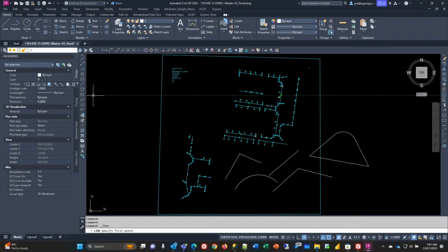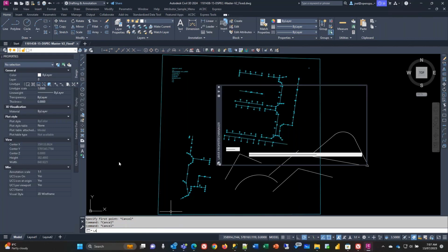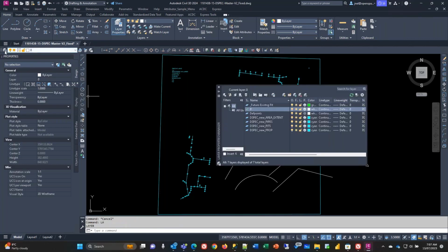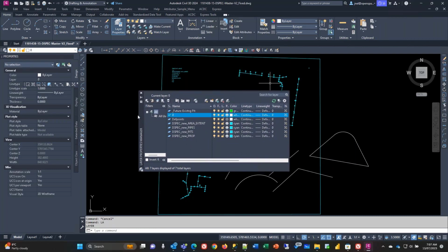later. So to get to the layers, what we'll do in there is, you can see there, I've got a layer properties. You can also, L was for line, LA is for layer. That will do that, or there's your icon for it. What that would then do is turn on your layer so that you can work with it. So once again, you can dock this, you can minimize that, etc.